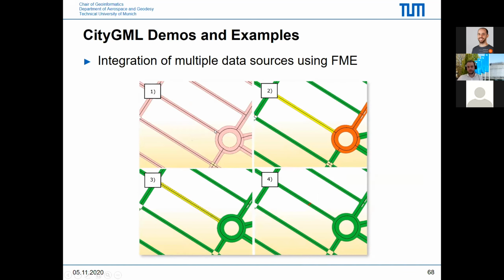This is a very simple example of what these spatial correlations looked like. We had the centerline dataset, and in this case, the underlying road beds with aerial geometries. You can see here in green, where a centerline could be correlated to a surface one by one, so to say. In this case, the surface under the centerline got all the information provided in the centerline, all the attributes, and so on. The orange example here, on the other hand, contains multiple center lines. So we first had a look at how long these center lines are. Are they just overshoots here, for example? Then we would get rid of them. And once we could clearly assign the leftover center line to the underlying aerial geometry, again, we transferred the information from the center lines to the aerial geometries.